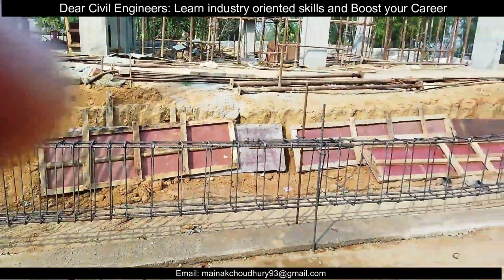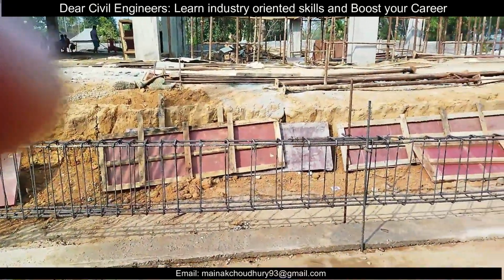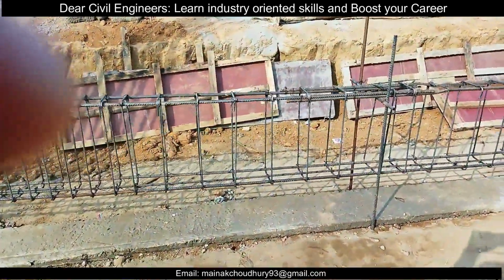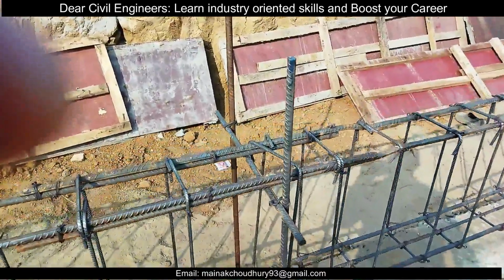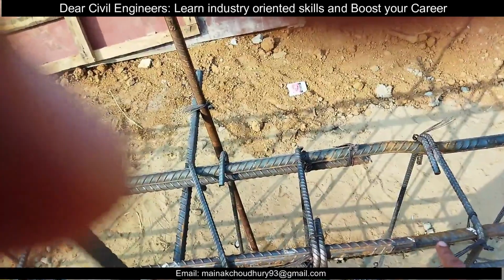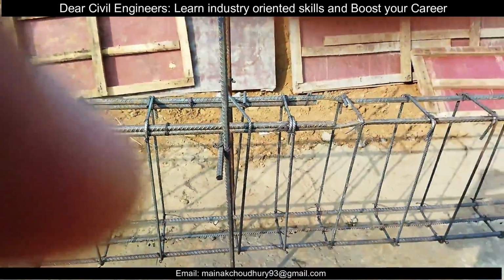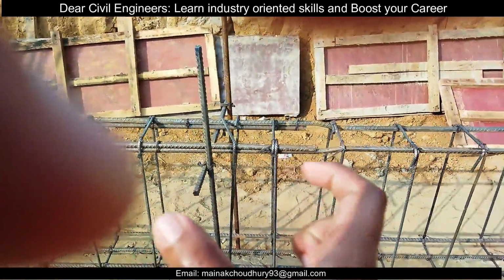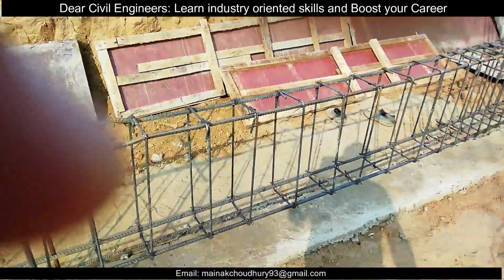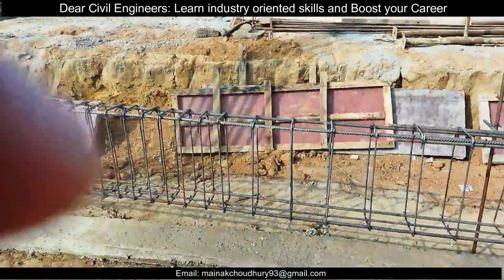So if you divide this particular span from here to here into 3 parts, L/3, L/3 and L/3, in the central zone the lapping can be provided, which is provided like this. You can observe here also for an idea. A slight bend is given here, and then the lapping is provided. And if there are 2 lappings, they should be staggered. One lapping for 2 bars, that is 50% of bars, will be given here, and 50% at another location. So as you can see, this is the work which is going on.